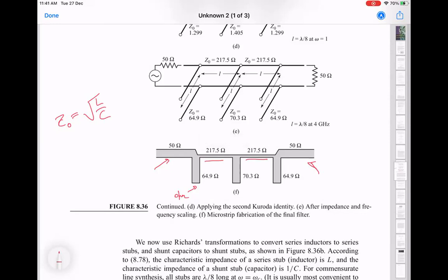But it is possible to use special materials. Now, this might not be possible to do with copper or gold-plated copper for conventional circuits, but using superconductors, you can actually construct transmission lines which have much higher impedance, because they use another type of inductance called kinetic inductance, which doesn't depend on the geometry. So you can get more inductance per unit length than you would get for a geometric circuit you are making. But that's a completely specialized type of thing. So that's what constrains these things.